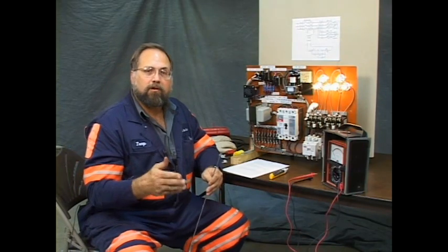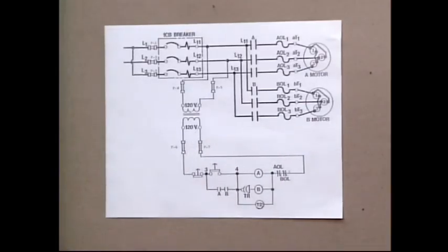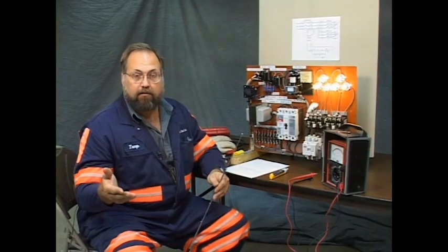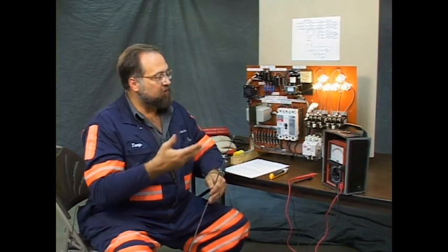You wouldn't want to latch a start switch on a motor control, because if you had an overload, say the overload operated, it would open and stop for the overload. When the overload cooled and the switch closed again, if the start switch was latched, it would just restart without someone having to start it.